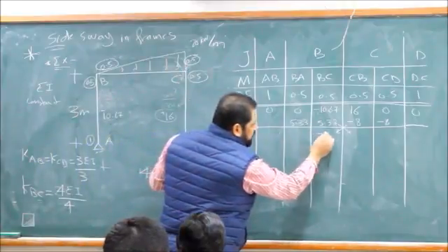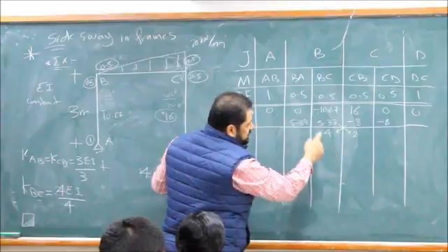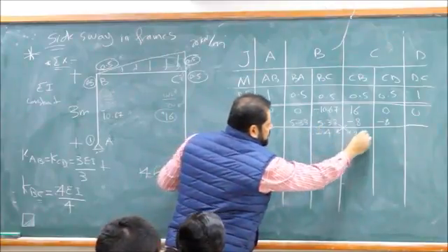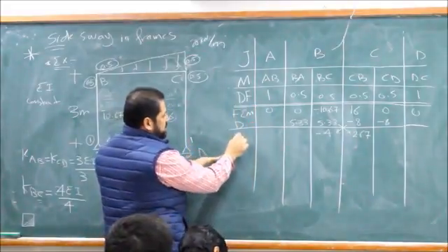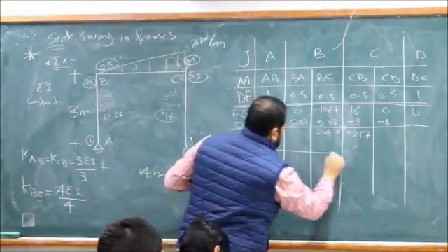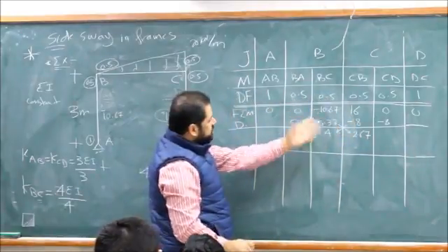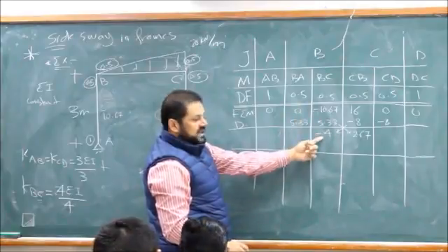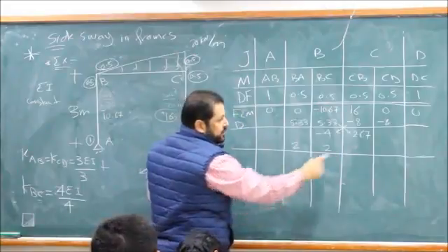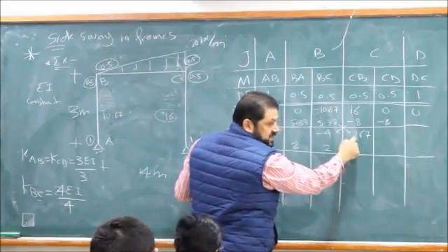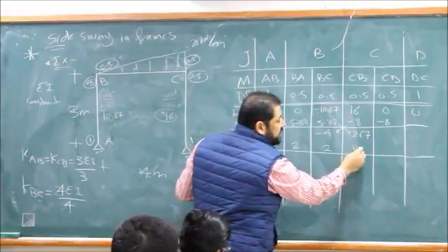So this is minus 4, 2.66, 2.67, positive. Now you have the same cycle. What you did here, you do it here. This joint has unbalanced minus 4. There will be 2, 2. This one, what's half of 2.67? 1.33.